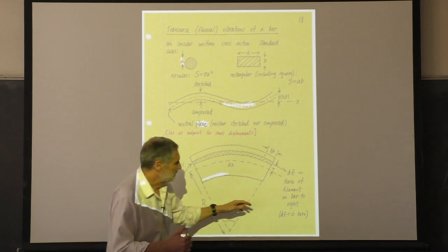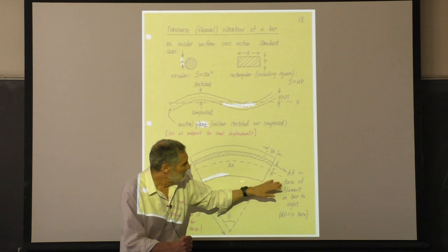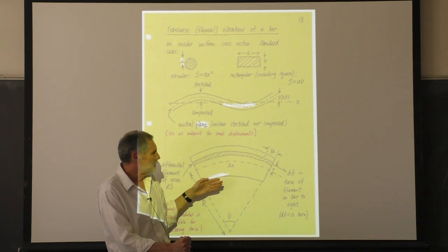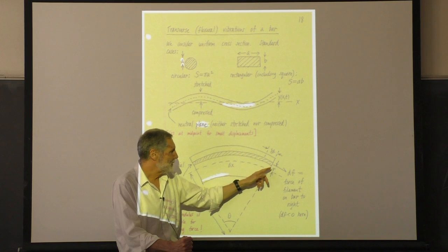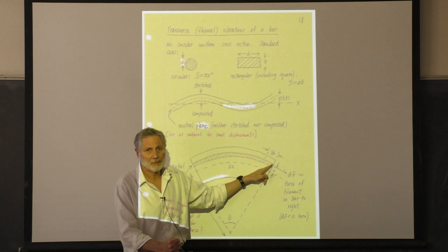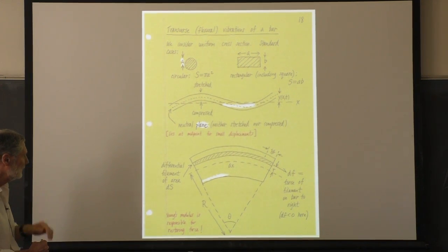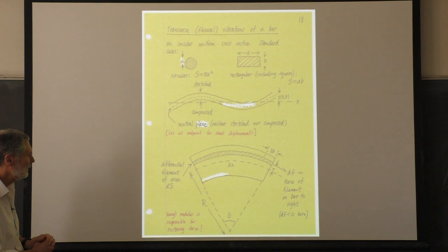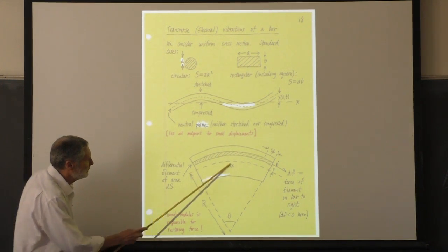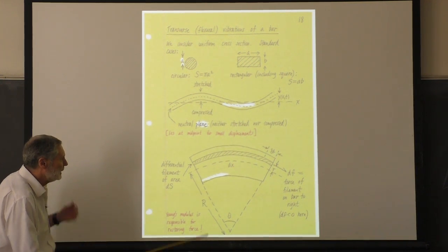And remember this convention that we used for longitudinal motion? By convention, this force here is the force of the left part of the bar on the right part of the bar at a point here. Remember that? We have to keep the signs straight here. Oh, and the neutral plane will have some radius of curvature here. We'll call it capital R. This is for the neutral plane.